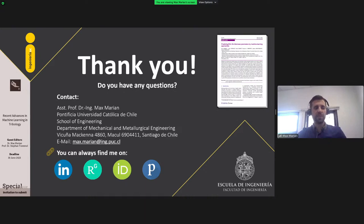on the one hand, for example, if you're in a very low load, or in the very rigid isoviscous regime, you have other effects dominating. You might, for example, play around with the stabilization of your numerical model, maybe the discretization, to have converged solutions there, which might influence the results on the other end.